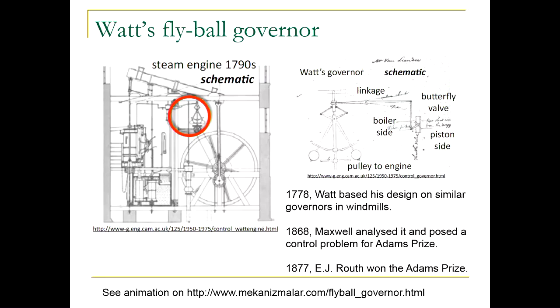People realized that depending on your design, how big these balls are, how long these levers are, how you design the whole system, you might either have very nice, stable behavior, where you really maintain the speed you want, or they go nuts, right? They would oscillate between very fast and slow, and break things.